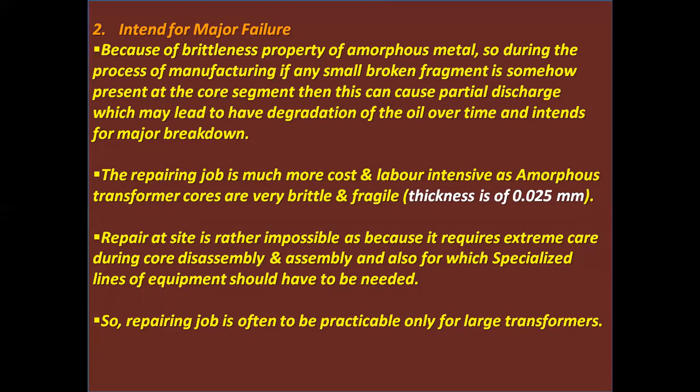The repairing job is much more costly and labor intensive as amorphous transformer cores are very brittle and fragile. Thickness is of the order of 0.025 millimeter.